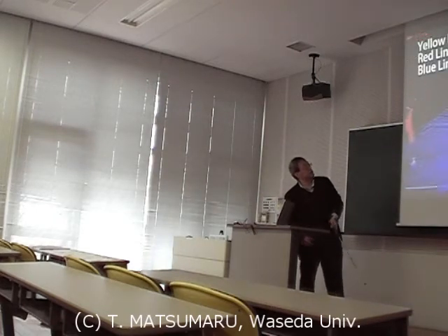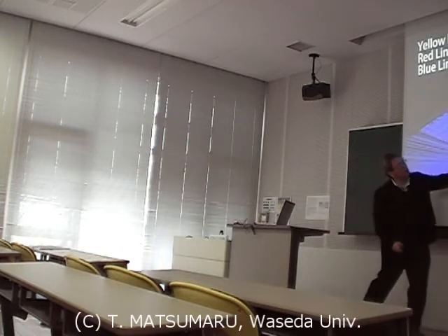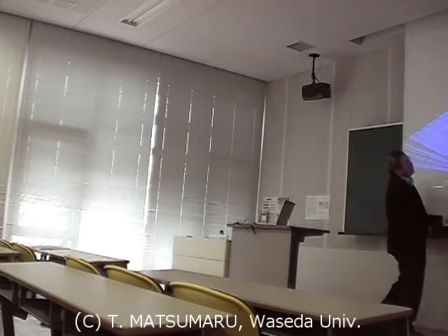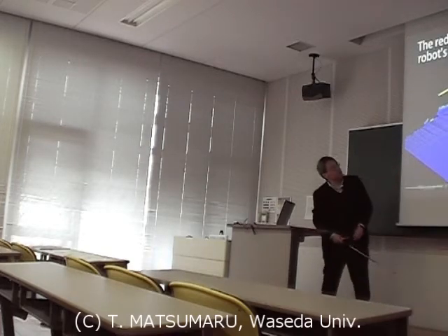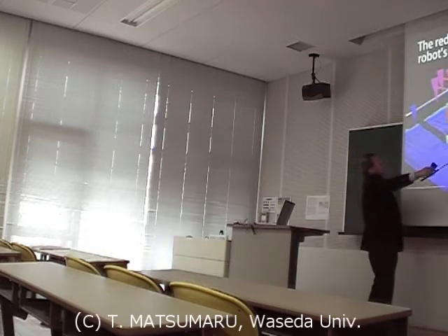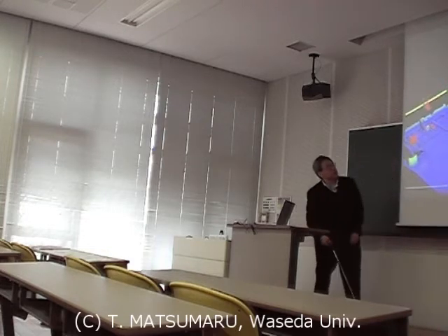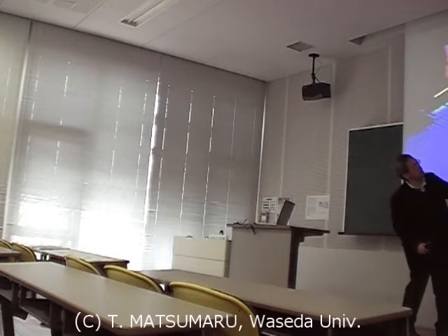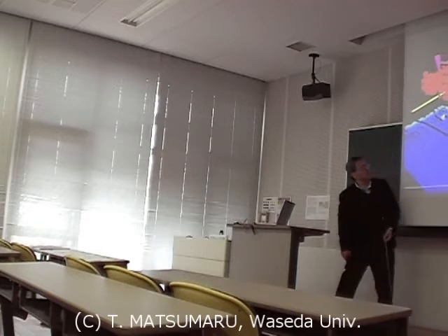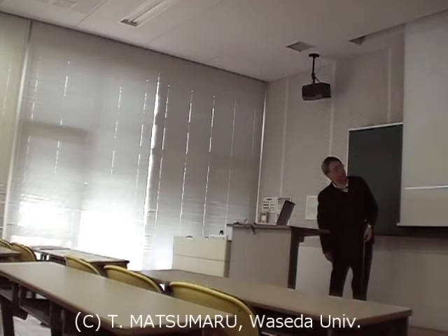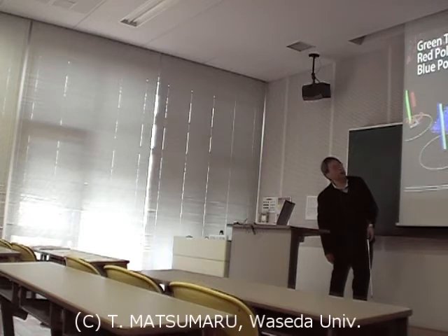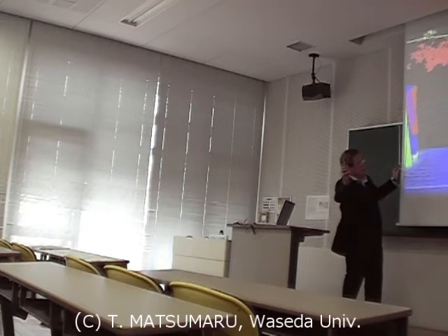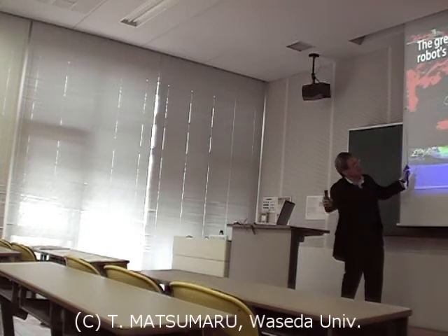Localization using the line. And then when executing the movement, all the surroundings are traced in real time, and some marks, the landmarks, can be detected and matched, and then the present position is slightly modified based on the map. It says tree landmark. The map is based on the preliminarily prepared three-dimensional map and the landmarks.